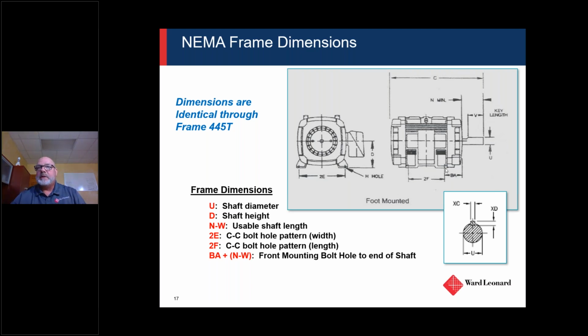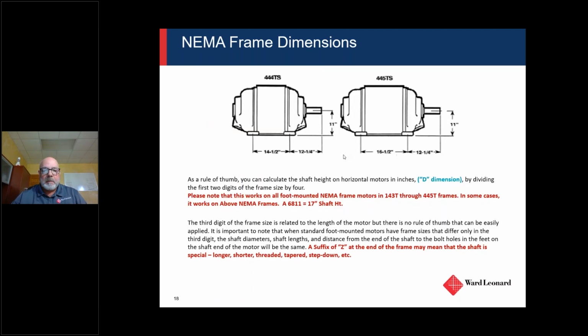What's that length? Right. So when you think about applying a replacement motor or even a spare motor, you might have spares. That's where we have to get those things right, because your base plate and your bolt holes are going to be set up for whatever motor you have pulled out of there, right? And even your couplings and all those dimensions are pretty important, right? So that's why we ask for those. It's so much better now that we can all say, give me these dimensions, and there you go. So we all know what we're talking about.